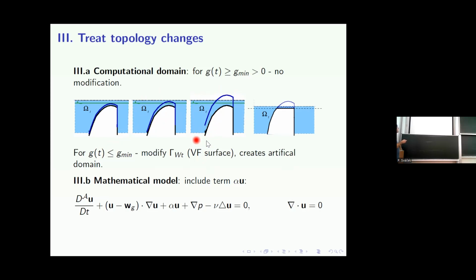So we somehow modify the geometry. This is basically shown here, for example, for this case, where we say, okay, just make this flat, and we keep the computational domain for the fluid connected by adding this cross area to the fluid domain, keeping it still undeformed. Clearly, this doesn't correspond to the closure of the fluid domain. So in order to force the flow velocities to be zero within the solid domain, we add this reaction term, or artificial porosity, with higher values of alpha, or it can even depend on the acceleration in this case. So we choose alpha being high, which makes the flow velocity zero.